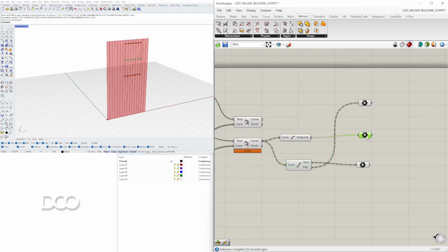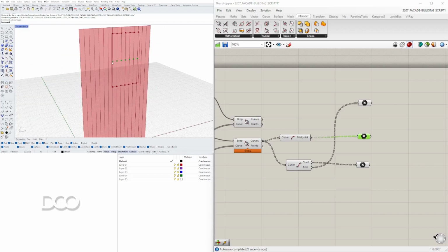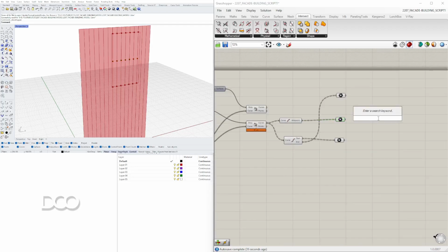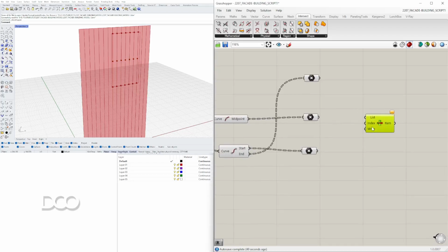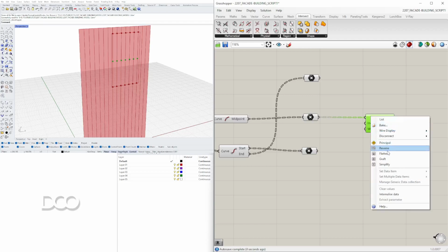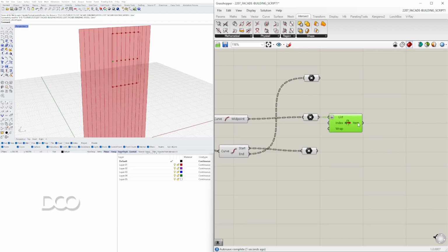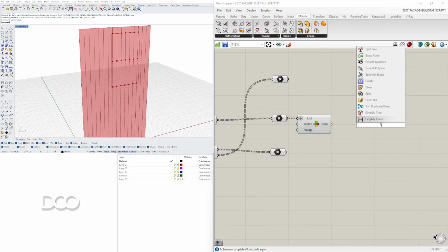Now what we need to do is take these points and we need to extract one of the points and scale all of these relative to one of the endpoints. So I'll go here to Item or List Item. And when we use List Item, we'll be able to pick one of those. What happens is they're here grafted, so we do have to flatten the input. And then here at the output, we have one value or 1 point that we can now use to scale. So we'll go to Scale.